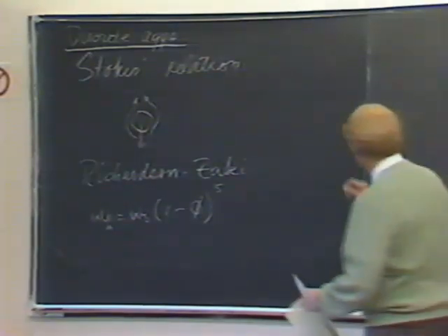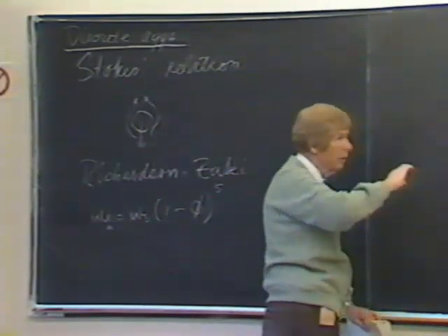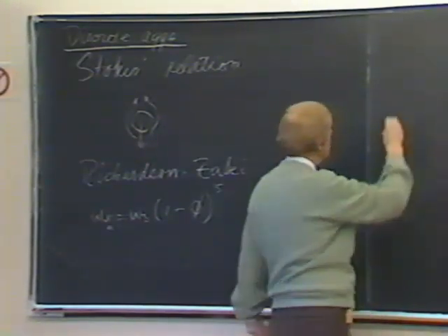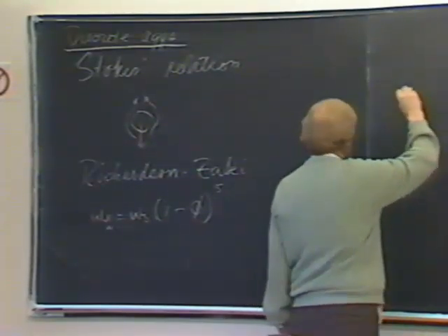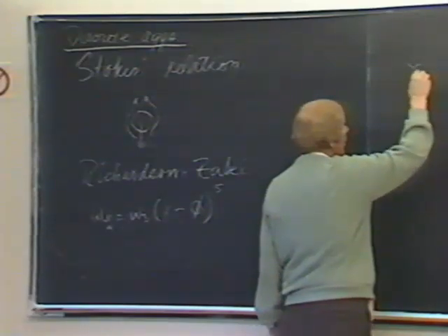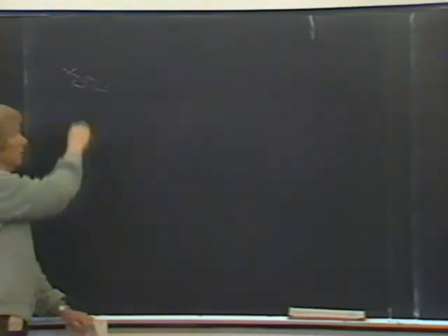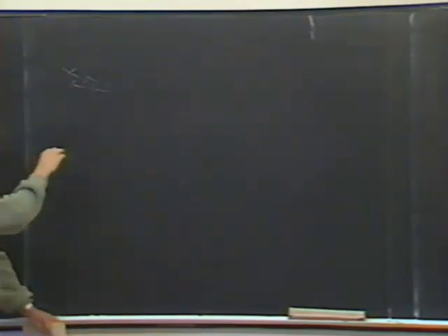When the particles all touch one another, that is, when the concentration is high and the particles can all form some kind of an open network, it might be some very unstructured network of particles. Then the particles may not settle because the settling velocity of the individual particles is quite low. So hindered settling, which depends on the settling velocity of the individual particles, isn't very effective.